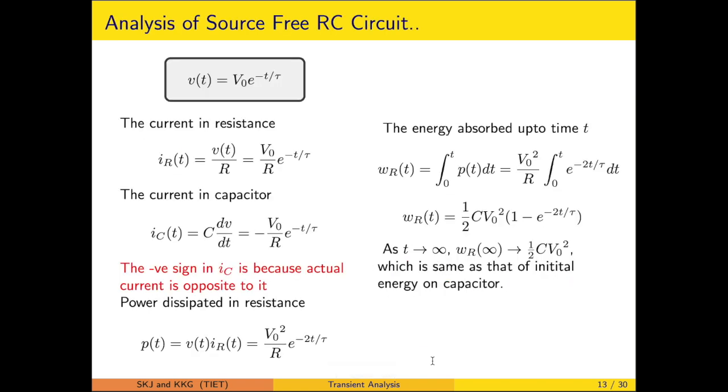So in the case of RC circuit, first point is to calculate the voltage. After calculating the voltage, we are free to calculate the current through the resistor and the current through the capacitor. Likewise, they are coming out to be of negative nature. So IC is negative to the IR. This holds true the KCL relation that we have worked out, but physically it suggests that the actual current direction is opposite to what has been taken as a reference.